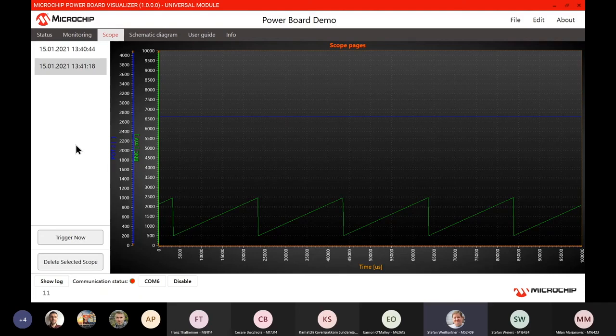Because with the real digital oscilloscopes that we are all used to, we can only measure some external signals that are coming out of the microcontroller. Franz, as I understood, sometimes uses an extra pin of the microcontroller to visualize some internal value and put it on a DAC output, and uses his oscilloscope to visualize what's going on inside.